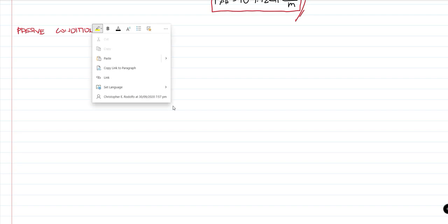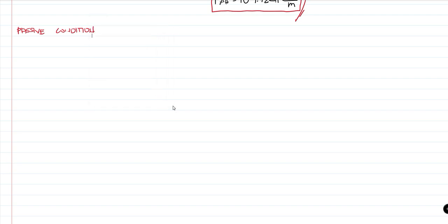So to get the passive earth pressure, syempre that will correspond to P sub P, which is equivalent to gamma H Kp. Yung gamma natin will still be 18.8 times the height, which is times 4.5, sorry, times yung Kp, which is 3.681.